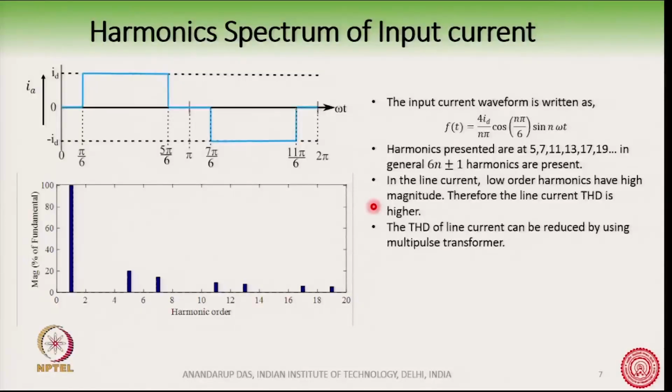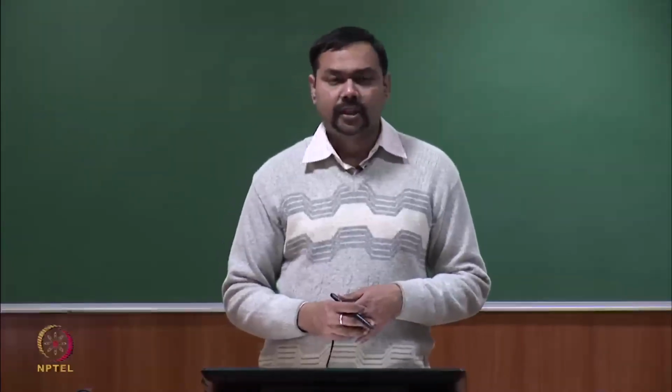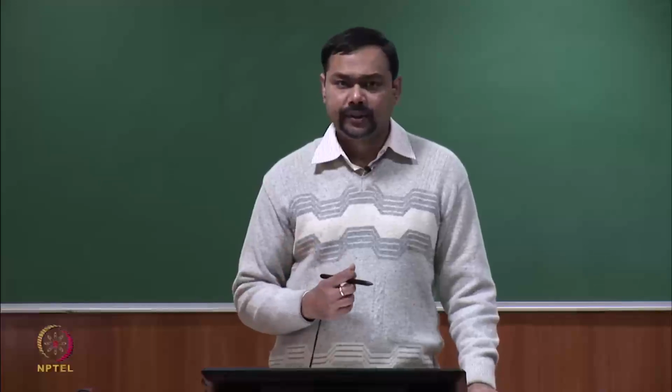Now, as I said, for low power applications this may sometimes be acceptable, because the total contribution of the harmonics is not so great. But when you go for, say, megawatt applications, the contribution of the harmonics is quite substantial, and we have to take care of it.